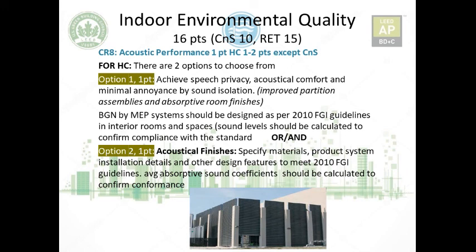Background noise by MEP systems should be designed as per 2010 FGI guidelines in interior rooms and spaces, and sound levels should be calculated. Not only design, but also calculate whether it is working as per the design or not. It should be complying with this standard. So this is option number one.